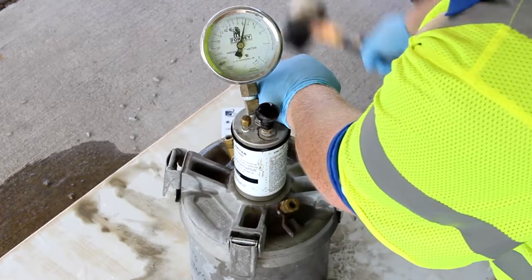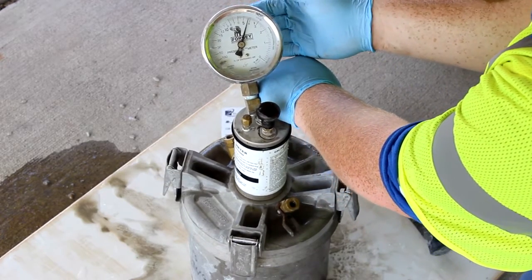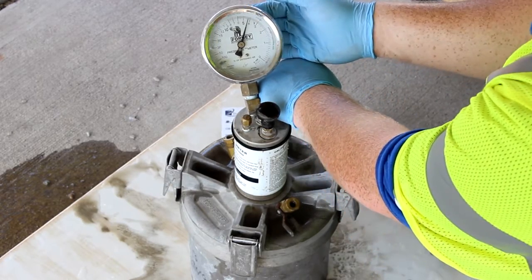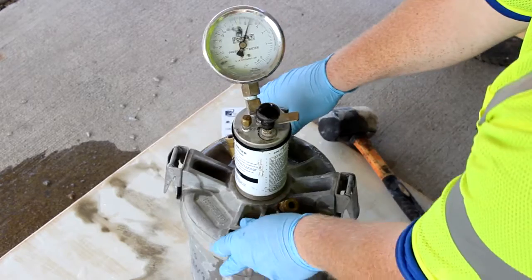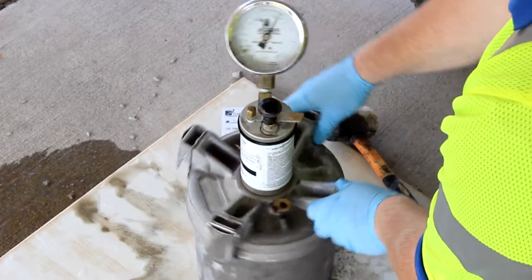Then, open the main air valve between the air chamber and the measure. Tap the sides of the measure smartly with the mallet to relieve local restraints. Lightly tap the pressure gauge by hand to stabilize the gauge hand. Read the percentage of air on the dial of the pressure gauge. Release the main air valve.